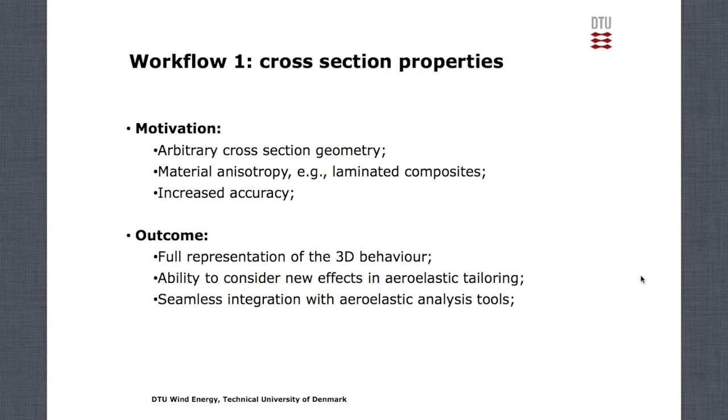The motivation to use BECAS is, as I said before, and I summarize here again, the ability to account for arbitrary cross-section geometry, the ability to correctly account for the effects of material anisotropy, and essentially the increased accuracy you gain by using such a tool. So you're able to much better estimate the overall structural response of the blade.